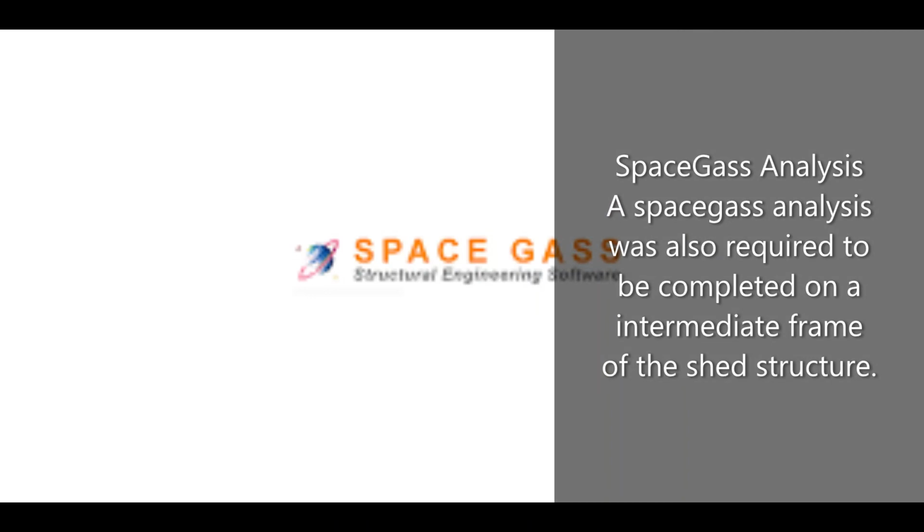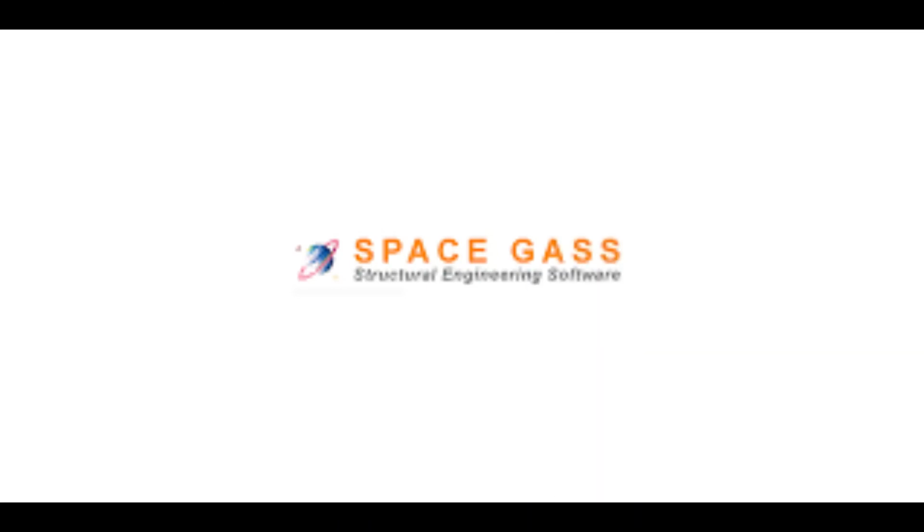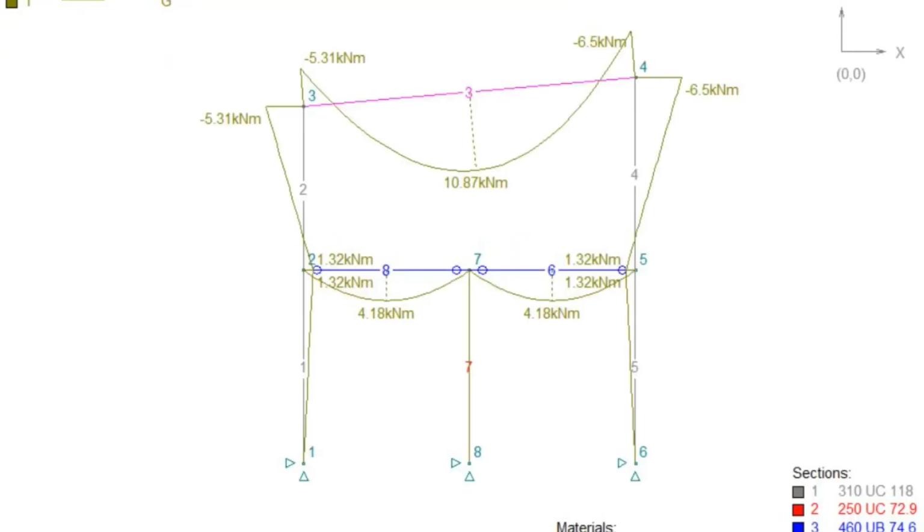Space Gas was used to create an analysis of the intermediate frame of the structure. Using Space Gas features, the analysis performed determined the bending moment, shear force, deflection and axial force. Then a comparison between the Space Gas model and manual calculations was made. As the Space Gas model was split between dead load and live load cases, the result differed. This is due to the manual calculation using dead load combinations which combined the two load cases used in the Space Gas analysis. AS 1170.0 uses ultimate limit state or load combinations which include safety factors and ensure safe design.